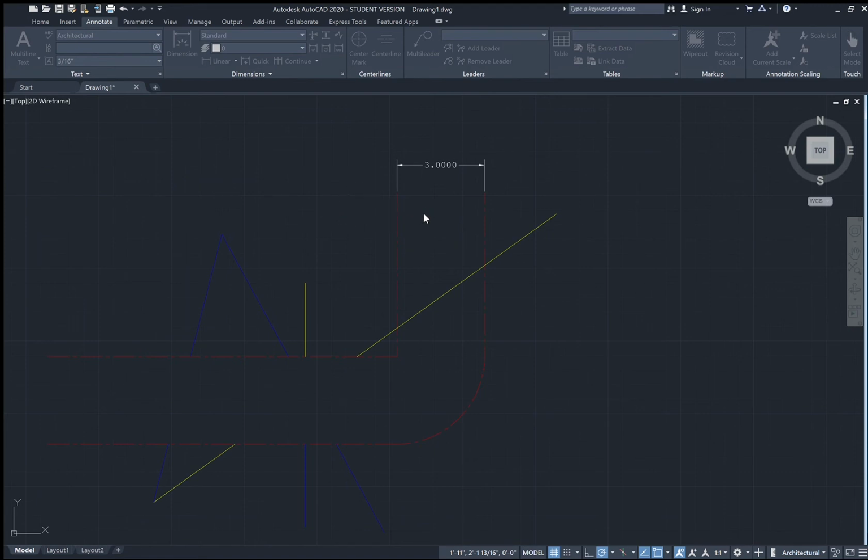The text color we can set by layer. This basically means that the color of the text is going to match whatever layer it's on. And so we have the arrowheads. All of this stuff is pretty self-explanatory. We can increase the arrow size so that it's more prominent. And when you're done, you can simply click OK. We can set our architectural style to current, just like that.